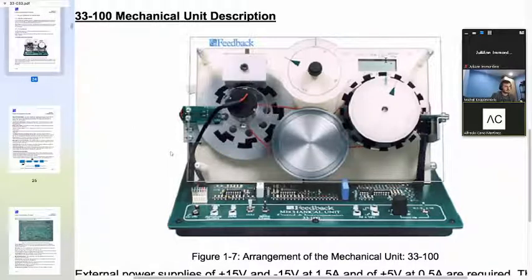You need a way to transform whatever physical characteristic you are trying to study or manipulate into some voltage, so that you can use circuits to compare the voltages and then map back to the original quantities. So think about this. What we are doing here is position feedback. You could use this as the altitude of an elevator or the attitude of an airplane, the angular position of a wing. So this could be mapped to anything.